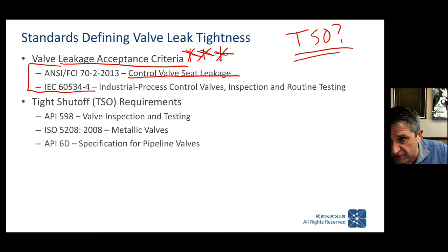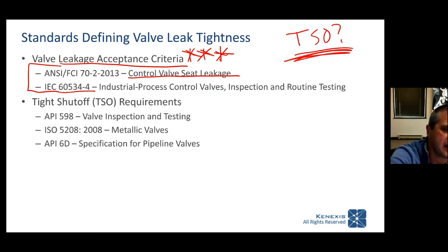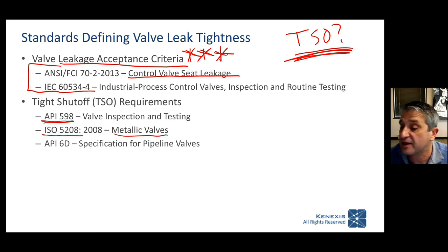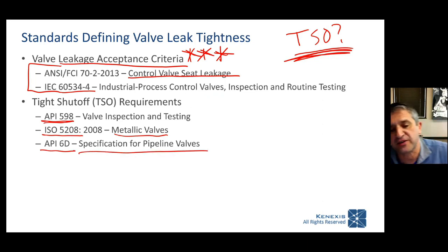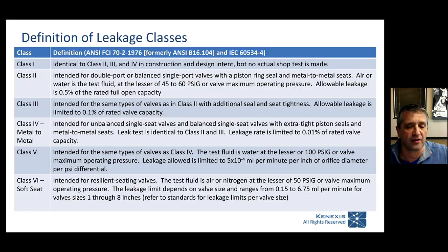Now, searching for that infamous TSO, you can find TSO in several standards. You can find it in API 598, valve inspection and testing. It talks about TSO. I'm going to hold back on telling you whether or not it defines what TSO means. ISO 5208, metallic valves, contains the phrase tight shut off, and also API 6D, specification for pipeline valves, also contains the phrase tight shut off.